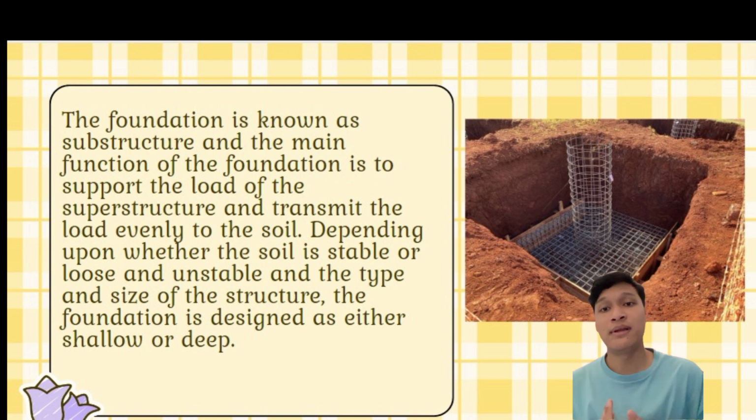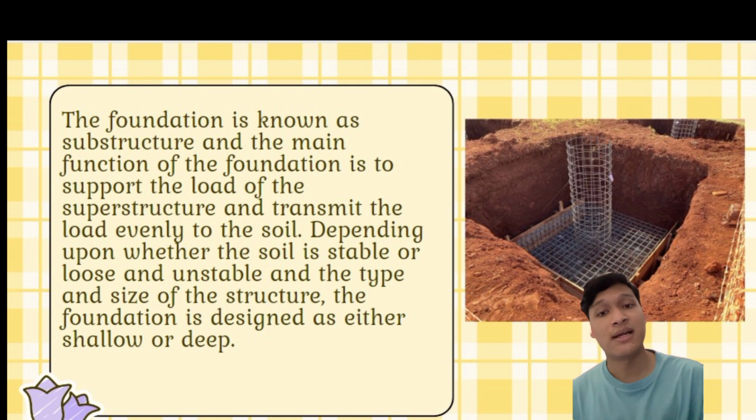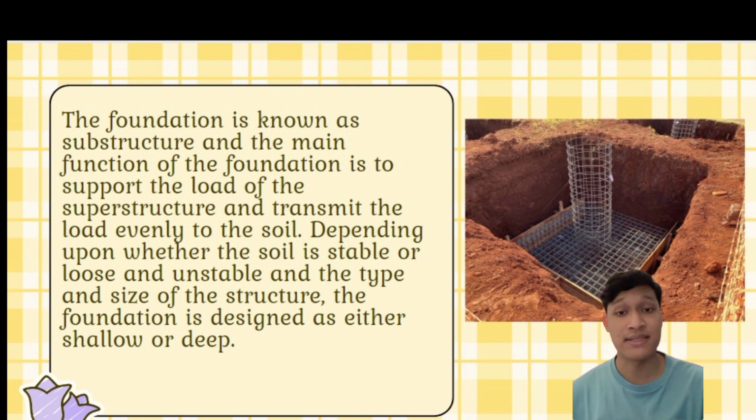So how can we know that we have a stable foundation? A stable foundation should bear the loads without sinking or settling more than an inch at the most. Even this settlement should be uniform under the entire building. Foundations are necessary to be strong and stable. The soil type of a particular area might not be solid, so inspection of the soil and the surrounding areas is necessary to determine the type of foundation that needs to be constructed before we build any building above it.